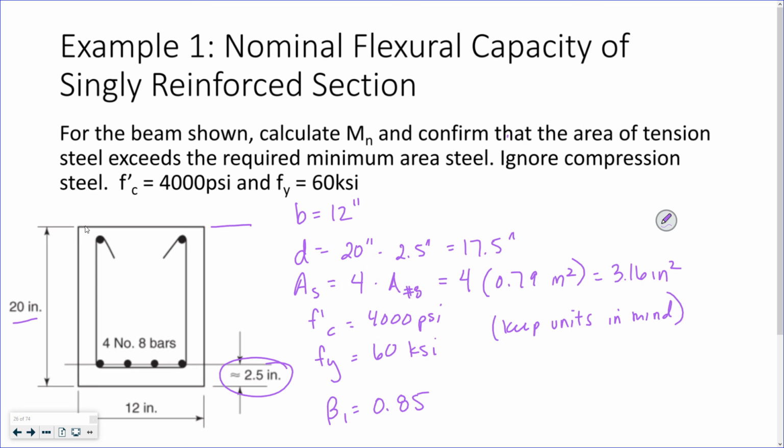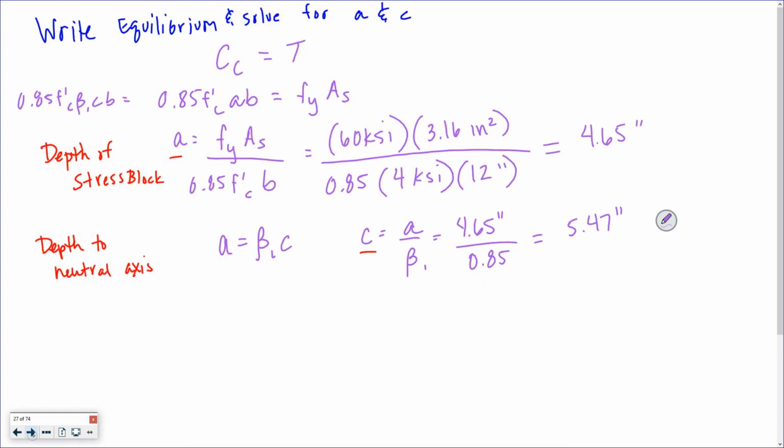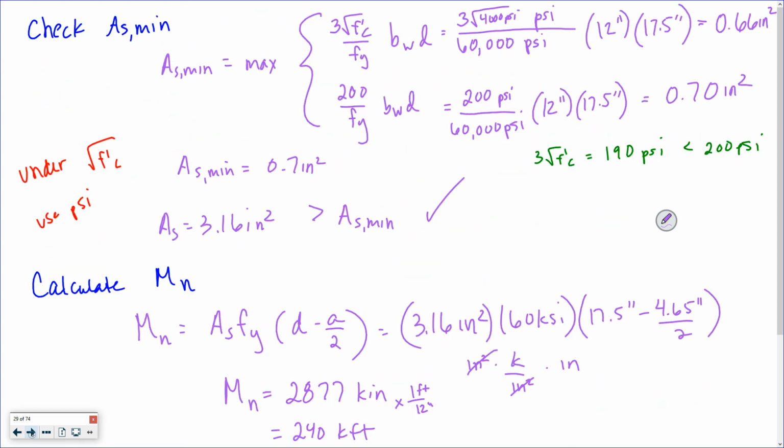We're ignoring the steel up here in compression. And it's a nice rectangle. The good thing about concrete is you're going to have nice rectangles for a lot of it. Maybe some T's, or little I-beams, but we're going to stick to nice looking stuff. So that is how, once you are given a section, you calculate its capacity. Okay?